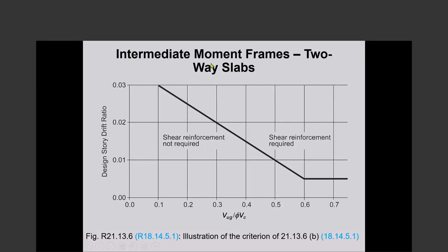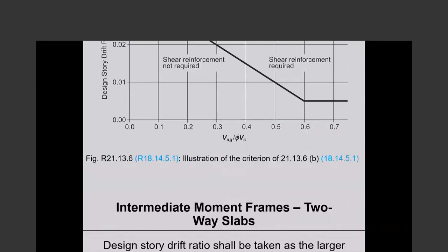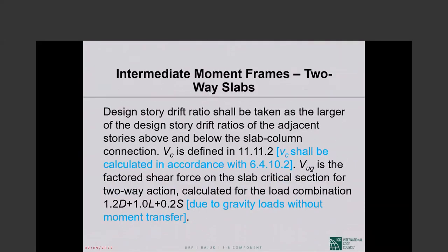Okay, so this is the ACI 318-08 requirement. It's a very, very important requirement. And if you provide this punching shear reinforcement, then you don't have to, I repeat, live with the limitation that punching shear due to gravity shall be within 40% of what concrete can carry.